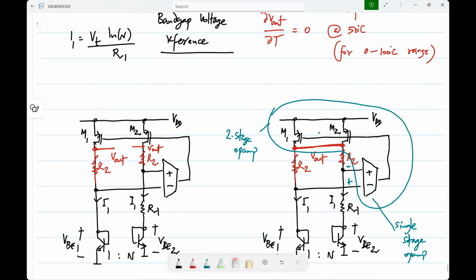So now we can get a constant voltage and we can scale this up to any value. Of course, it's not always that you need 1.2 volts. You may need something else, but we know how to make amplifiers, right? So if we want to make 5 volts, we take this 1.2 volts, use let's say an inverting amplifier with a resistive ratio that gives you 5 by 1.2 as the gain, and then that's it, you're set. Any amplifier, inverting, non-inverting, whatever. Any questions about the voltage reference?